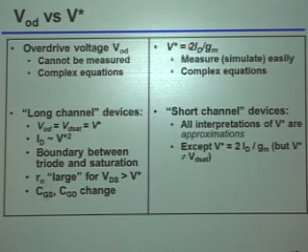Right? So the trick here is that now, because I defined that V star to look similar to that VOD, I can still try and make interpretations of what's going to happen to my transistor characteristics as a function of V star. In other words, if I reduce the V star, well, this is really by definition, my gm over ID is going to get better, right? But by intuition, I could say, if you reduce the V star, transistors are going to get slower, in other words, you're going to have more capacitive parasitics. Similarly, if I reduce the V star, then in general, the drain to source voltage you'd need to maintain a certain output resistance should also go down.